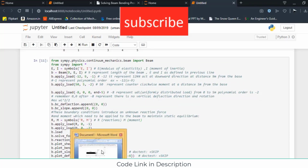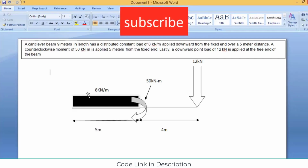Here a cantilever beam of 9 meter in length has a distributed constant load of 8 kN per meter applied downward from the fixed end over a 5 meter distance. A counterclockwise moment of 50 kN meter is applied 5 meters from the fixed end. So this end is currently fixed. And lastly, a downward point load of 12 kN is applied at the free end of the beam.